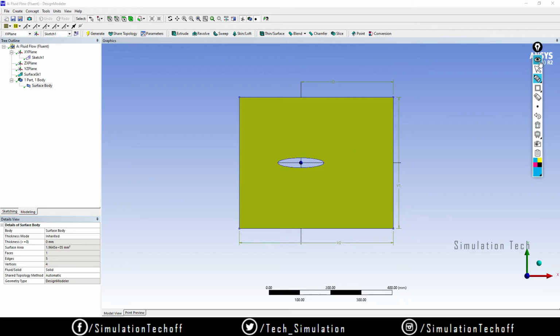It's an air domain. Air is a fluid, so not only water or liquid is a fluid. In terms of Ansys Fluent or CFD, water, any fluids or air, we call it a fluid. So I'll shift to Fluid. Later we assign that material.